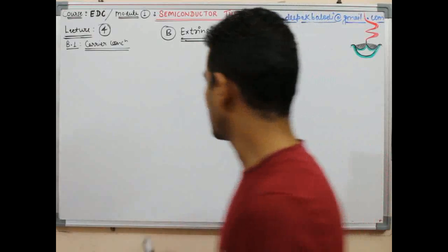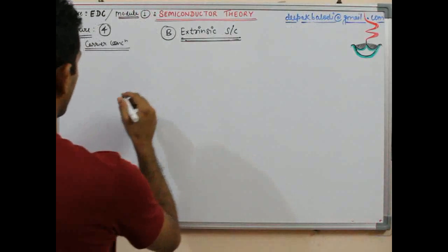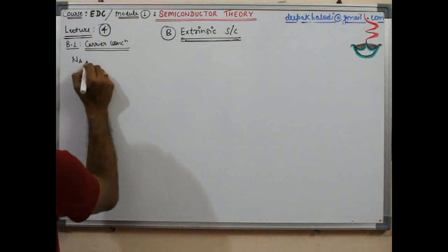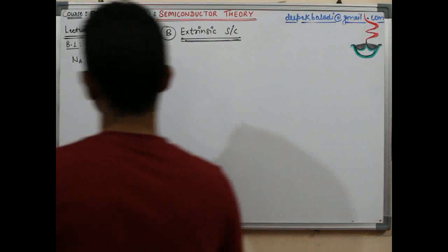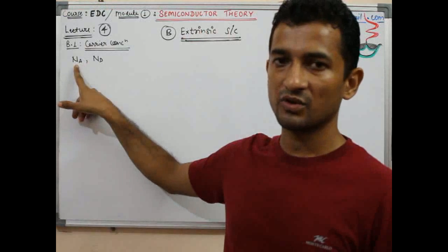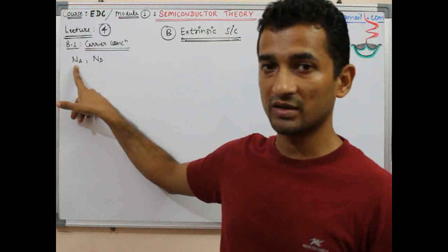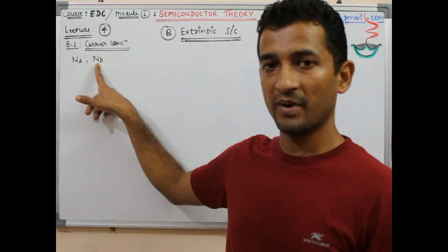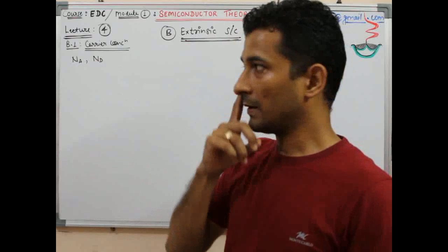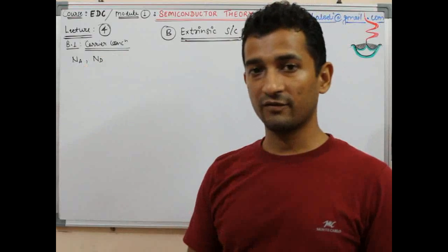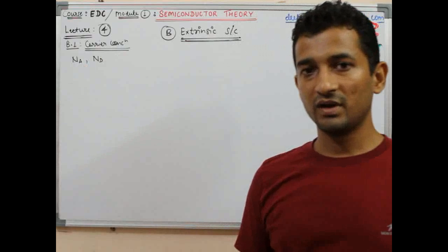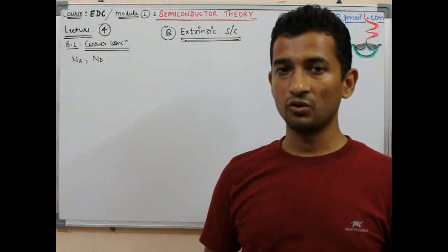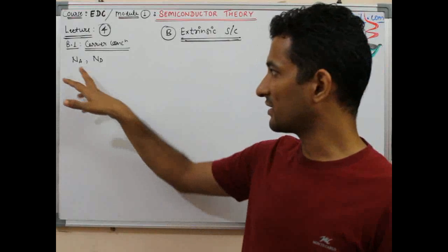So let us quickly look at this. Let us assume that we are doping with Na and Nd. These are the impurity concentrations: Na, the number of atoms of trivalent impurity per unit volume, that is per centimeter cube, and Nd, the number of atoms of pentavalent impurity per unit volume, that is per centimeter cube. So those many atoms, and by default we are always considering a case of complete ionization. Until and unless told otherwise, we will always assume complete ionization.